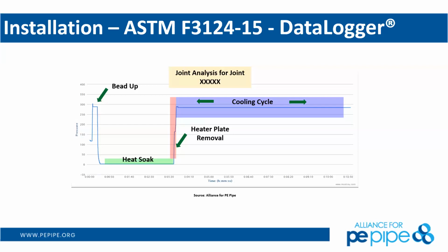The process of a butt fusion is very simple. You have several steps. After you face it and clean it, as we saw earlier, and you have the square ends, you're going to put the heater plate in, and you're going to do what's called an initial bead up, to make sure all the surfaces are contacting that heater plate. Then once you have that initial bead up, which is very small, you release all the interfacial pressure, so it's just touching that heater plate.